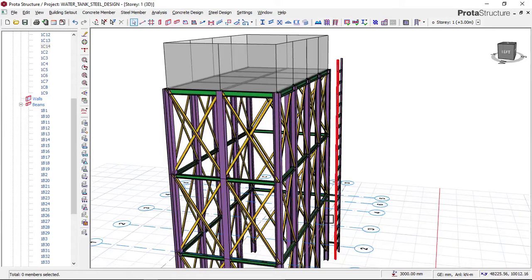So we do that on our plan view. Go back to our plan view right now and then click on this to take these properties, and then we click on this and input this to be 3000 and then 3000. Don't say update, because if you say update, it will send this one upward, and we want to insert a new one. So you just click on this and then click on this. Next thing, again, we want to input at the level of 6000. So we put it again 6000 and then 6000 and then we click again.